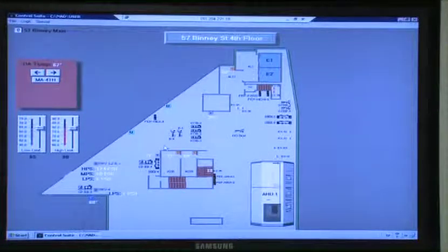Well, hold on. For the VAV that serves the elevator lobby, you have two VAVs that serve those electrical rooms that you see in the middle where the stairs are. The two fan coil units that you highlighted there and there: one is above the Cabelco compressors, that's the thermostat there, and then the other one is over by the steam station. And those run on temperature. If the temperature in the space goes above a certain setting, whatever your set point is on the thermostat, it comes on, and then when it goes below it by a differential, it's gonna shut them off. So normally they're off, they don't run all the time, they're gonna cycle on temperature.